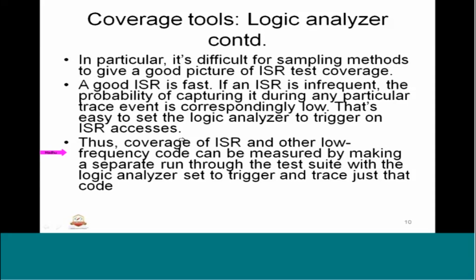Trigger on it, capture the data of what the ISR is supposed to do, and analyze the captured data with the logic analyzer to check whether the ISR is capable of covering all the intended results.